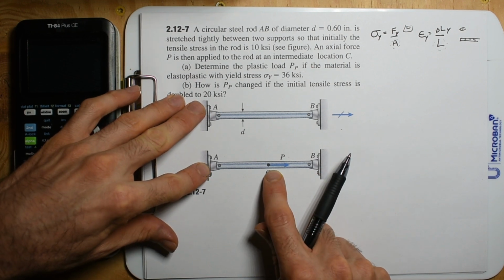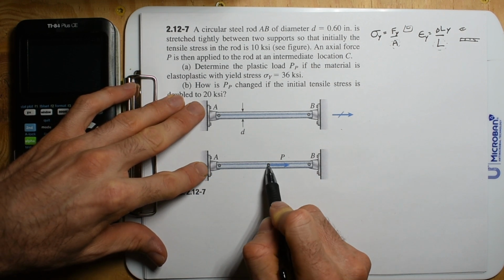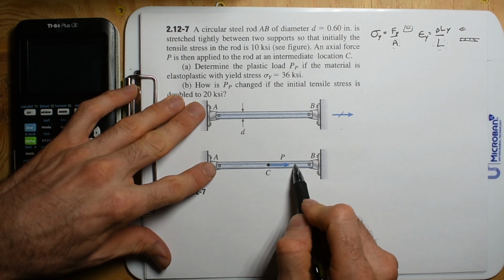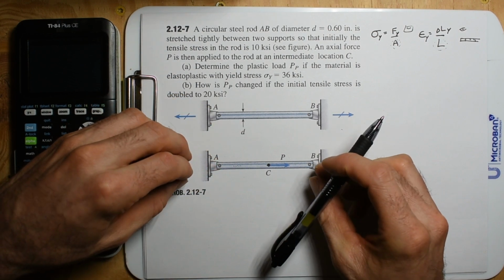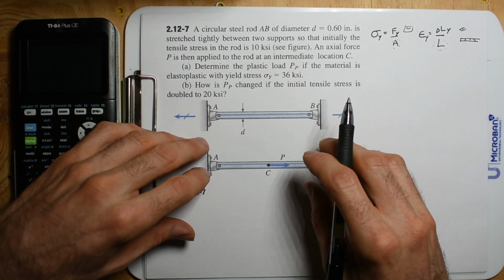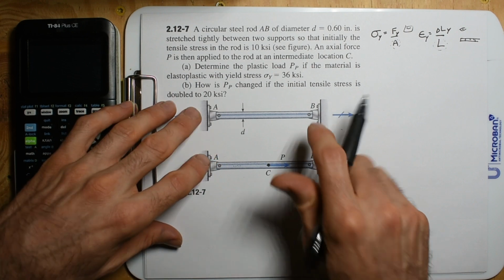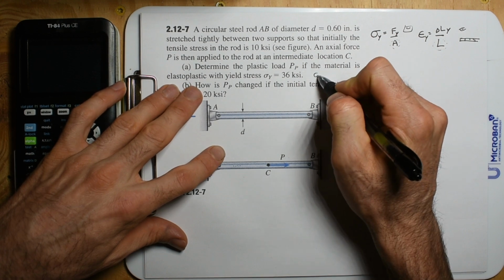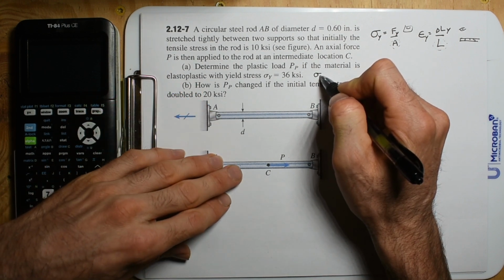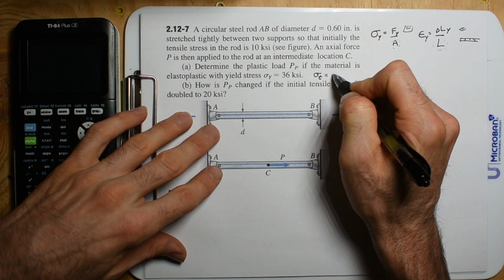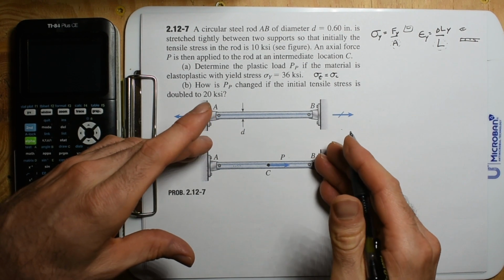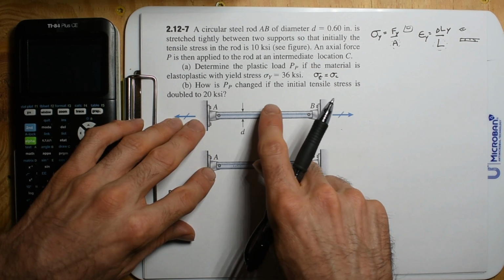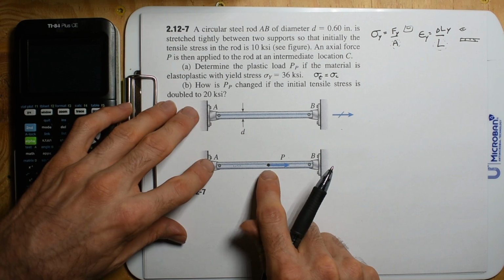And this problem was real easy because if we pull it in the middle, this part of the bar is resisting this force, and this part of the bar is in compression and it's also resisting. This doesn't say it's steel at all, but this is just assuming tensile stress is equal to compressive stress, and that's the property of steel. Now if this was a concrete bar, oh hell no, this problem wouldn't be as simple as doubling this. So that's what you're basically doing.